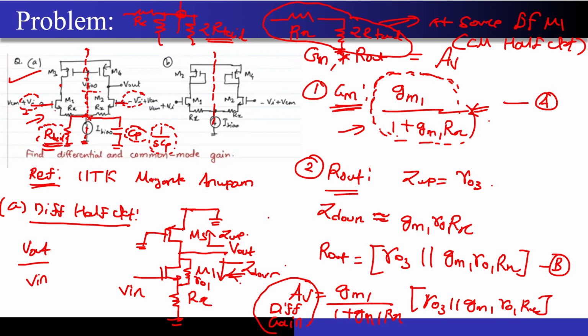Now for this particular transistor at the source, you can see that you have Rx, you also have a Rx over here. Correct? And then you have impedance looking at the source of the MOSFET on this particular side. So now this particular source, of the transistor where input has been applied, will be degenerated. Through that degeneration impedance, you can calculate, if I apply an input over here, I have a R0 looking up, correct?